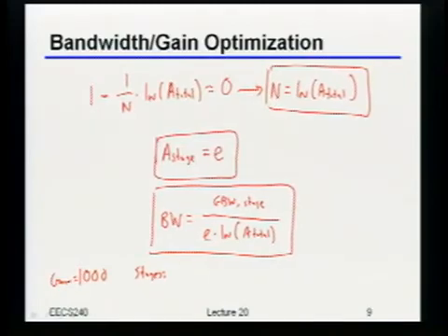2.3n. There we go. So remember when I said that it's 2.3 tau per decade for settling? It's the same thing here. Every factor of 2.3 gives you an order of magnitude. Okay, so I need 3 orders of magnitude here. So basically that's 3 times 2.3. So roughly speaking, I need 7 stages. By the way, you probably really do need 7 stages because 6.9 stages I'm not exactly sure how you build. Okay, so I'd use 7 stages for this thing.